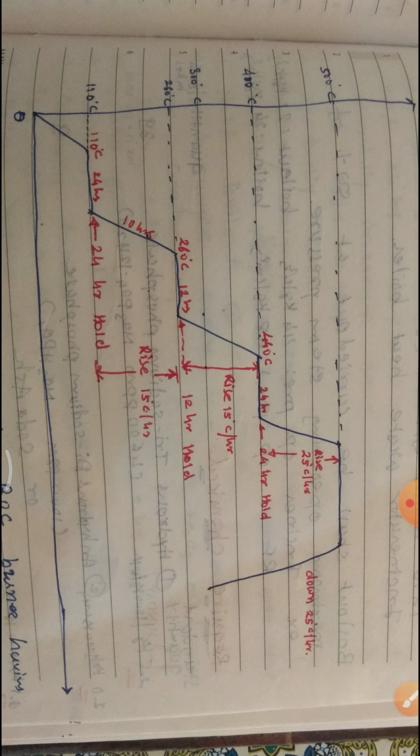After the 440 degrees centigrade hold is finished, raise the temperature at 25 degrees centigrade per hour up to 500 degrees centigrade and maintain the temperature at 500 degrees centigrade. During the increase and while maintaining, keep the waste heat boiler pressure at 22 bar by opening and closing the vent valve of the waste heat boiler.